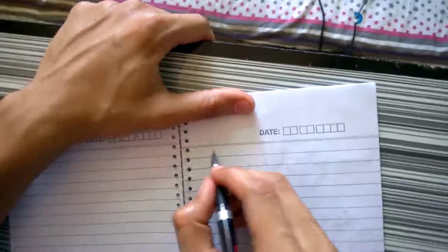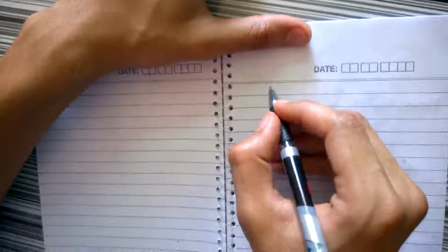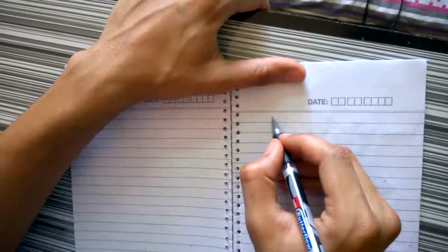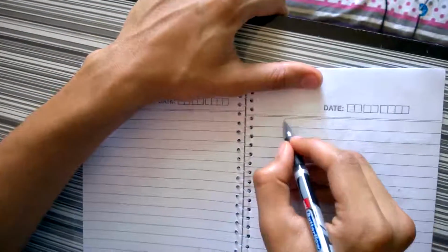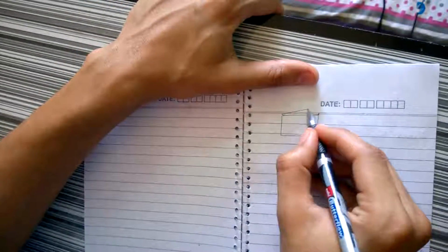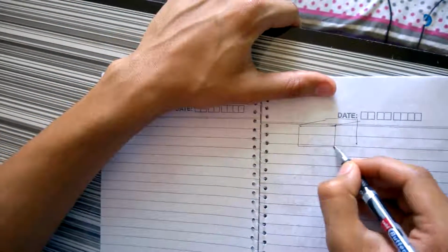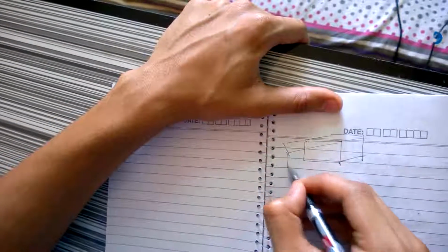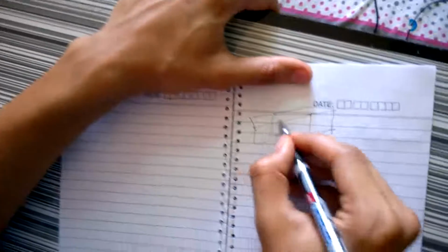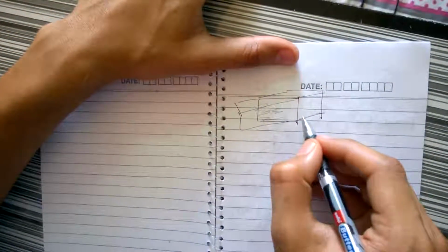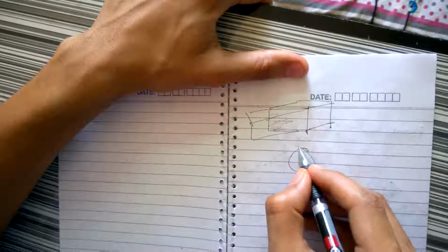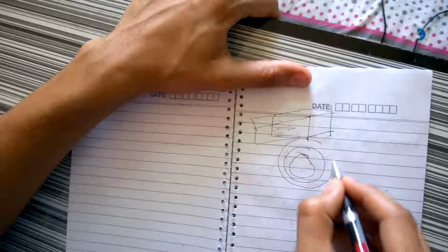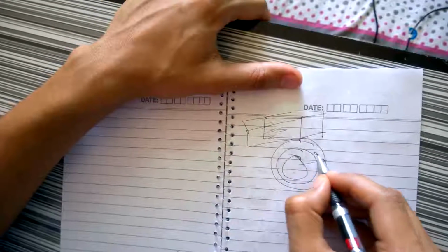So to quickly understand the theory part of it, the theory says that when you have a wall and you add insulation material to it, it essentially does not change the surface area. The face area does not change in case of a wall. But if you have a pipe and you're putting additional insulation around it, you find that the outer radius keeps increasing, right?